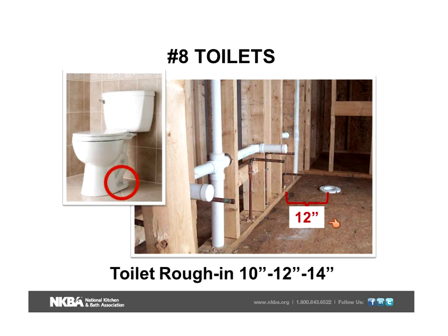Now, what that means is from this back wall to the center line of the closet flange, that is 12 inches. Now, you may find some that are 10. There are some that are 14. Most of them are 12. Here's where you get in trouble.